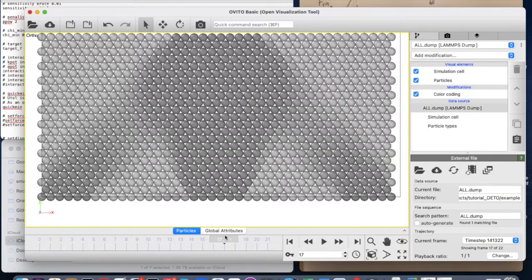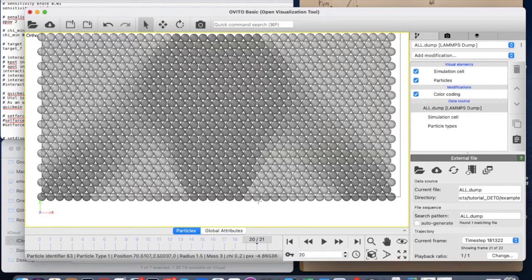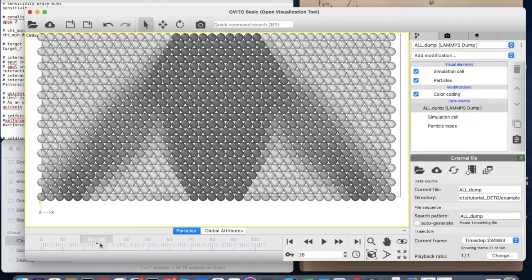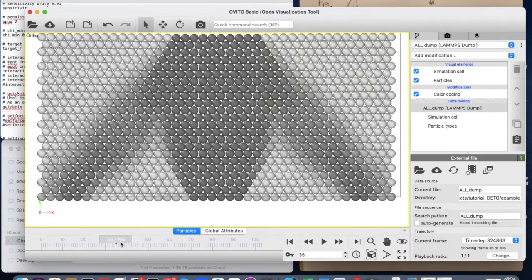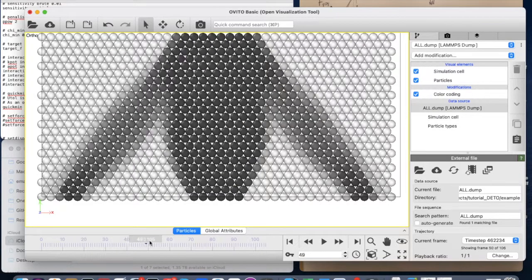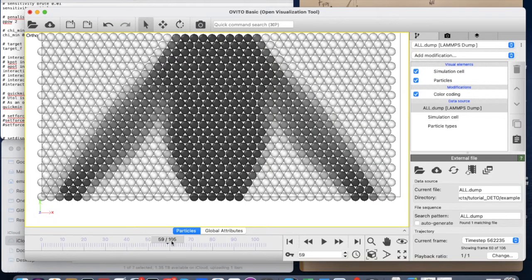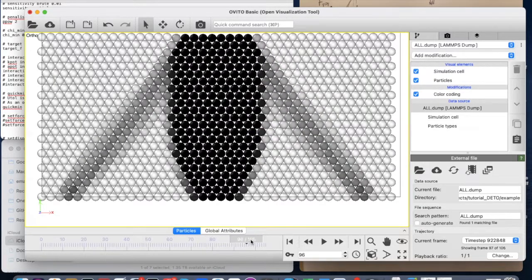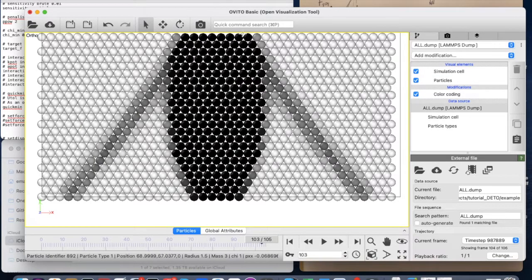And this is what we are seeing happening here. Again, it's deflecting, look at the top here, it's again deflecting down until reaching the minimum, and then again this will create, we're at step 21, a new configuration, and so forth, every time moving the xi towards a 0-1 solution, and every time repeating this imposed deflection, to measure the forces and so the energy, the strain energy in the system.